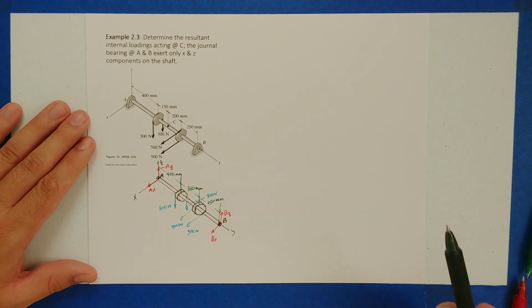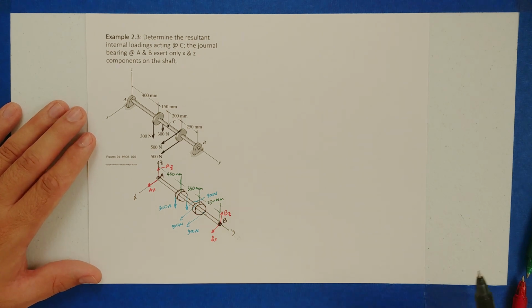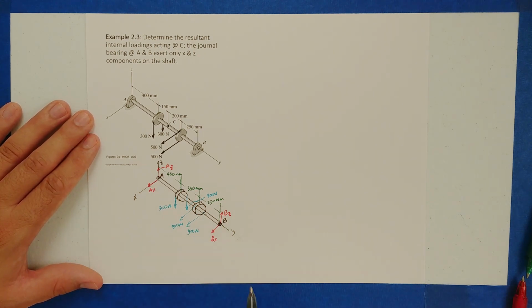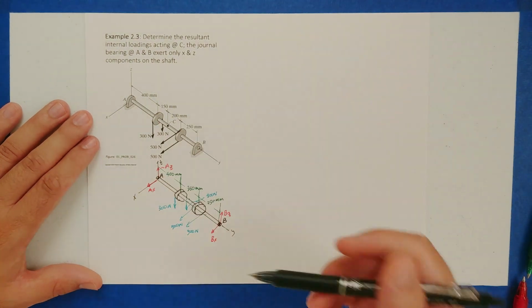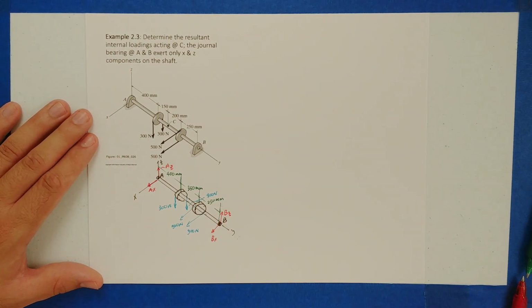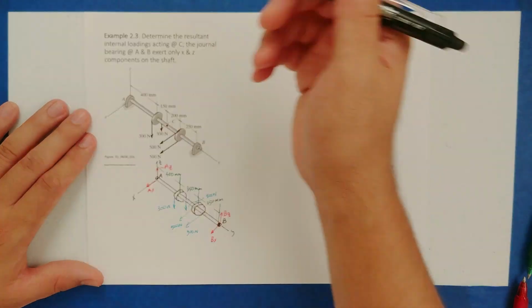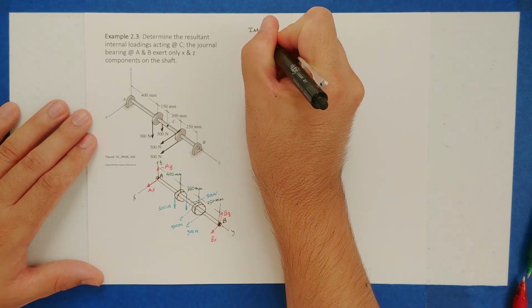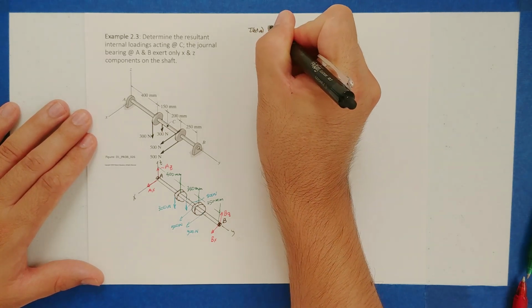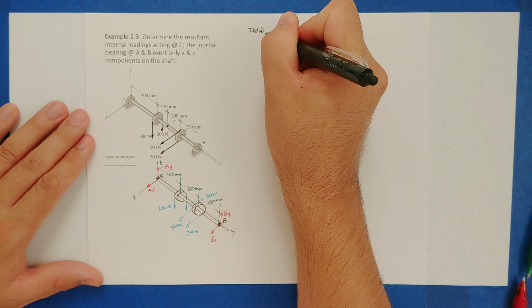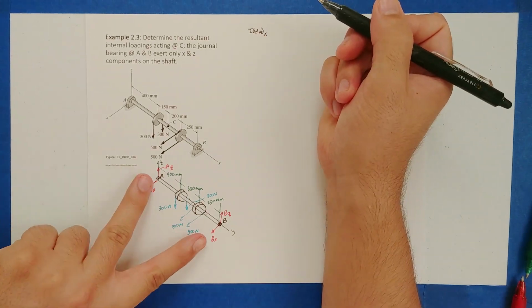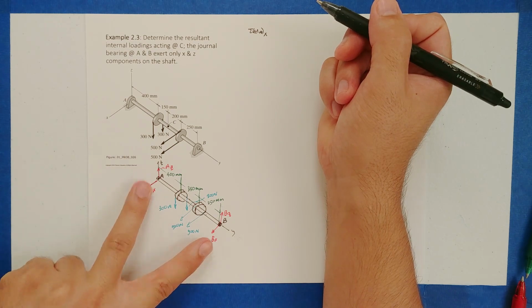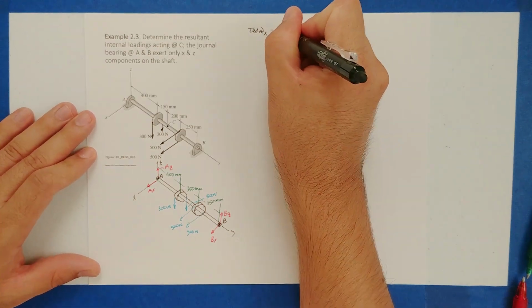The first question is at which point? Well, the point that has the most number of unknowns. Here, A and B both have two unknowns, so either A or B is a good point to start with. So let's go ahead and start summing moments at point A. Specifically about which axis? Let's go alphabetically. The sum of the moments about point A, about the x-axis. So we're looking for stuff that's going to make it swing kind of like that. All right, we're going to set those equal to 0.